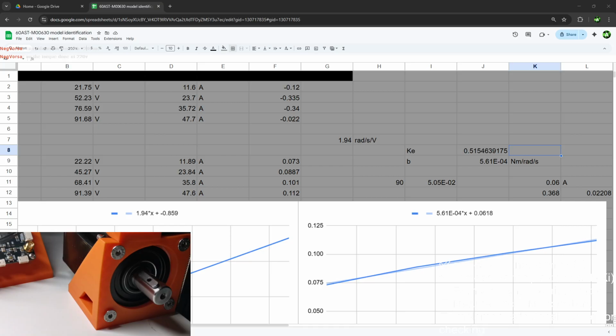So it doesn't matter that the motor is 220 volts. I can still measure it at 24 and get exactly the value I expect to have. And this value will stand even at 220 volts, if it makes sense. And this will be in volts per radian per second.